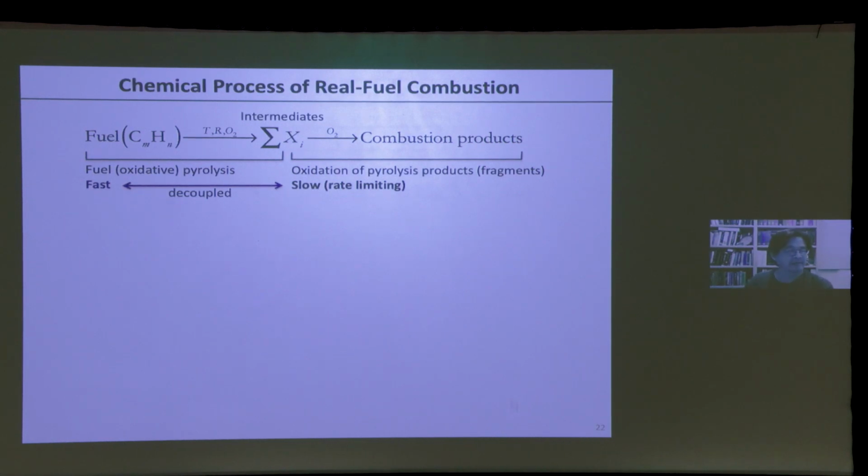So if you look at this physical understanding, how would I put a model together? I would jump through all of the large set of reactions describing how fuel gets to those intermediates, okay? And it's unimportant how long it takes, because you remember for this shock tube problem I said earlier, ignition delay time is 700 microseconds, dissociation time of the fuel is 20 microseconds. If I'm way off, off by a factor of 2 in fuel pyrolysis, so rather than 20 microseconds of dissociation time it's 10 microseconds, the total error in the overall ignition delay time prediction is simply a few percent, okay? So the point here is, this first part, you can simplify it. The second part, you have to treat it very carefully.